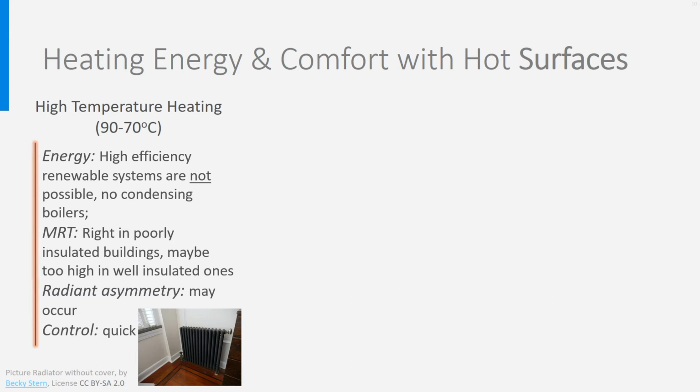There is, however, one nice thing about it, and that is comfort. In general, people love this high temperature source, and most important, in old, not well insulated buildings, it helps compensate for much too cold walls and windows during cold days. In short, it increases the mean radiant temperature, MRT. However, it may also increase radiant asymmetry, and in very well insulated buildings, it could cause a too high MRT.